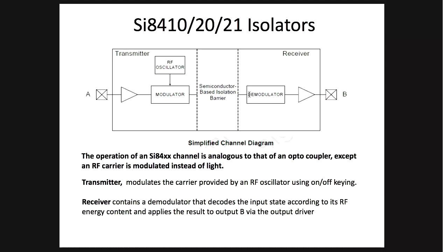Capacitive got not only noise problem, when your frequency is increasing, you may have parasitic components. But then these isolation techniques are not suitable in the gigahertz range, high frequency. Usually people use them in the megabits per second regime. There are some isolation, but that is not based on the capacitor. So if you want to make a very high speed one, what will you do?